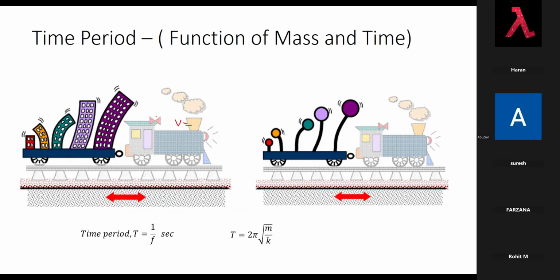What we need to understand here is, I just simplified this to different single degrees of freedom. So each system will behave differently. Each system will deflect differently, depending upon your building time period. Mathematically, building time period comes to one formula, which involves mass and K. Mass is the mass of this one, K is the stiffness.